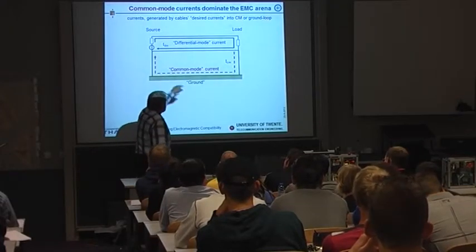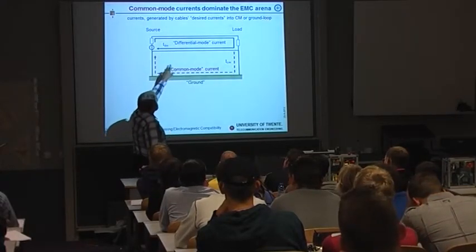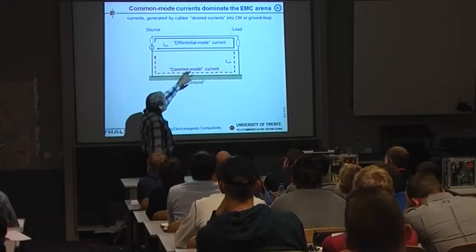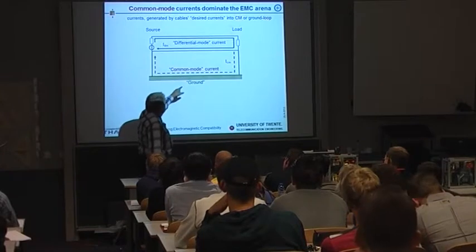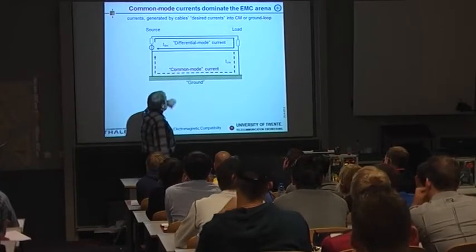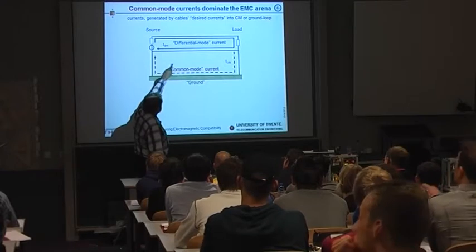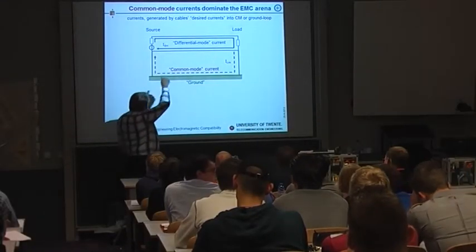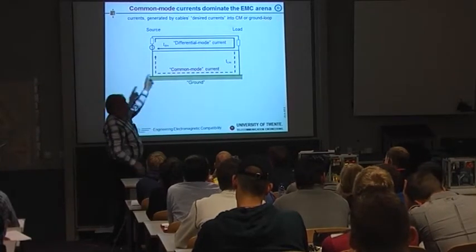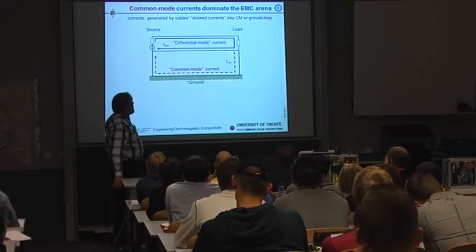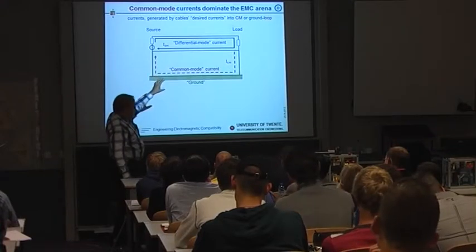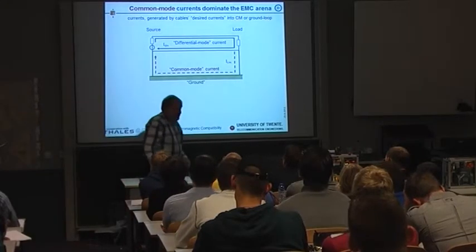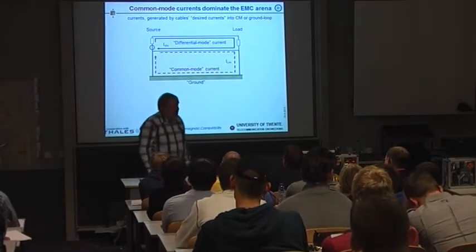Okay, this common mode current is usually small. There's amperes going up there, and here a few milliamperes, microamperes, going to the ground or another cable. But if the current goes here, due to Kirchhoff's law, that means that the differential mode current is not identical. The current going out is a little higher than the current going back because some of it goes another way. So if you measure around the cable with a current clamp like that, you can measure the same common mode current on the cable, and that's why you can make the picture like this.